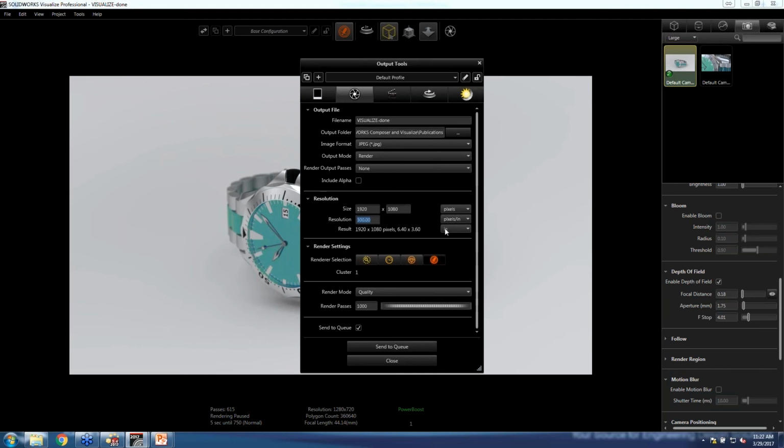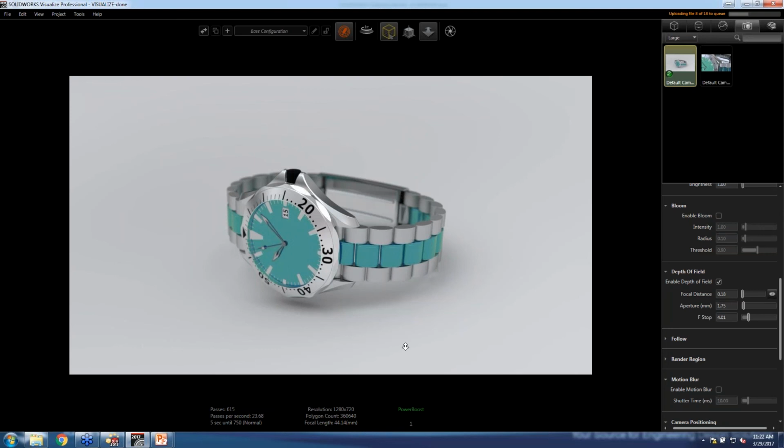That's not bad. And we could turn that up a little bit. I think for this purpose, because we want to output it pretty quick, we'll just leave it at 300, and then 1,000 passes works. So I recommend at least 500 passes when you do an output. 1,000 looks pretty photorealistic. 2,000 is right in that ballpark of looking about as good as it gets. Anything above that will get better and better, but you're just adding more passes without adding any more quality to the image. So it just takes more time without any real gain from there.